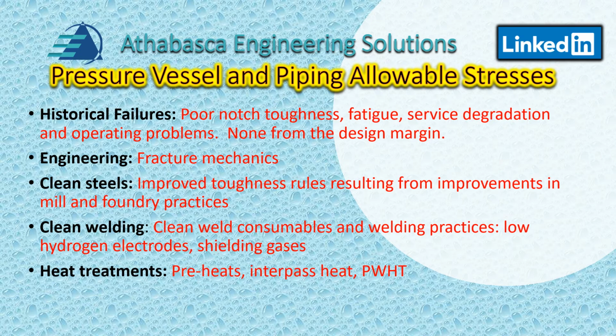We take into account preheats, which are pretty much necessary for everything nowadays, and interpass heat as well, for conditions like, for example, chrome moly steels, and post weld heat treatment requirements as per code, or prevention of cracking. And so there's a great deal of understanding about this.